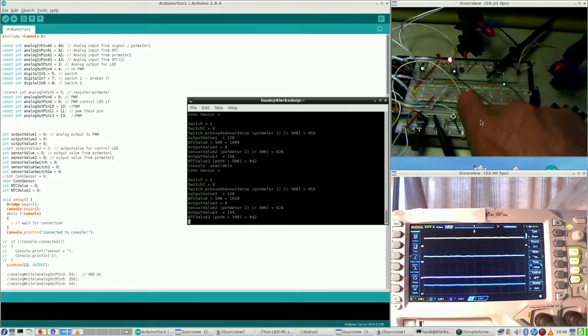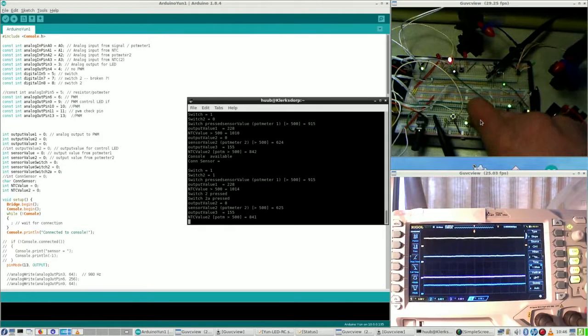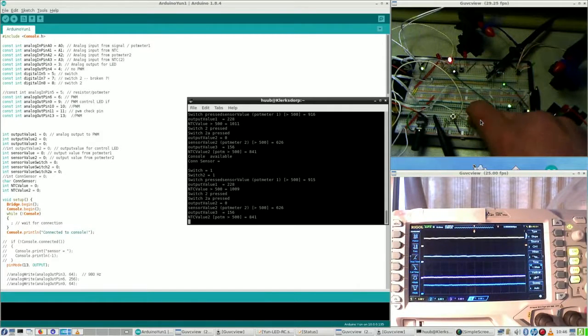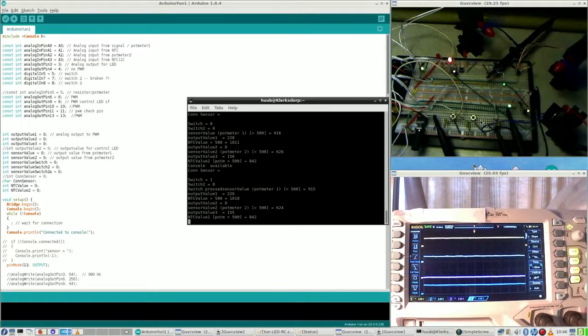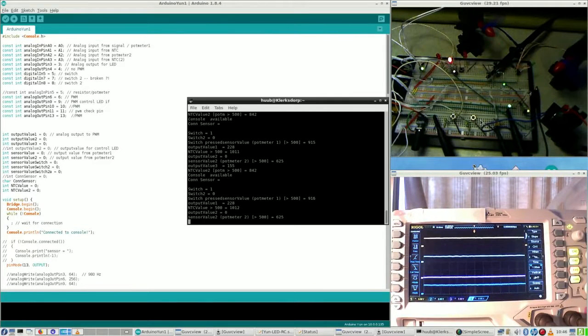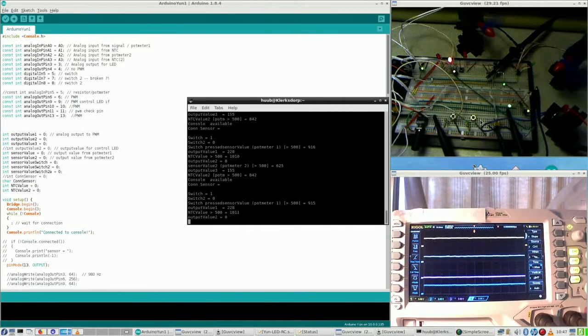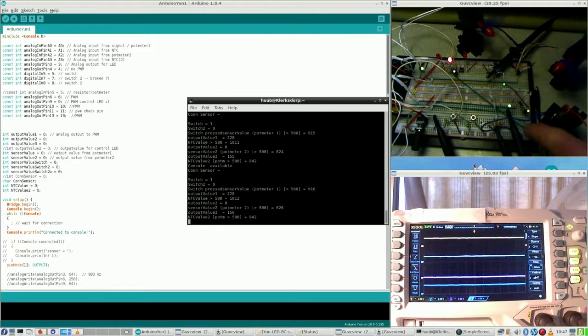Alright, now it works, and that should work for the right hand side propeller, which doesn't work either. It should send a 0 signal to the pulse modulation, making the motor stop, but apparently something is wrong with that. This part of the circuit is out of order.